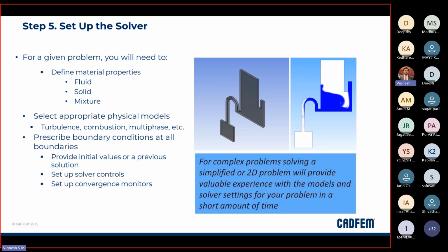And second, we also need to plan what turbulence model to use. Generally, yes, SST k-omega is a good default. It's good to go with, but I also need to think about whether there is room for another turbulence model. If we are looking for flow separation, in that sense, what turbulence model is the best? We need to make sure of that before we go to the setup.